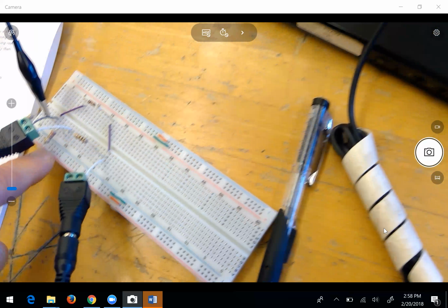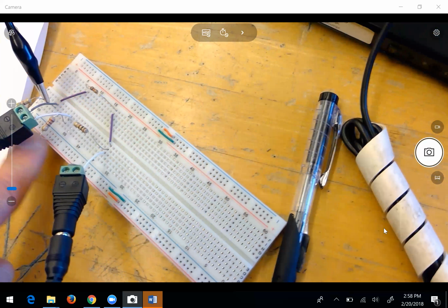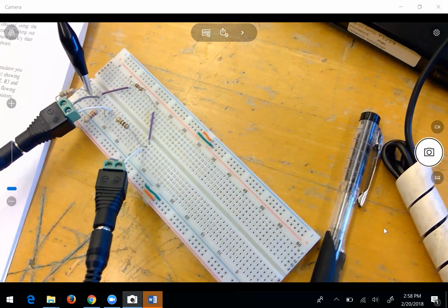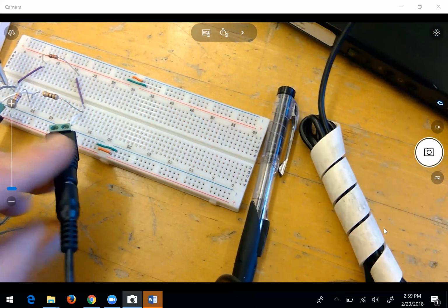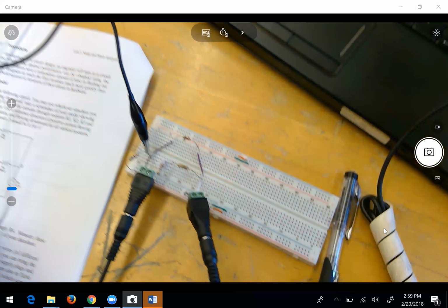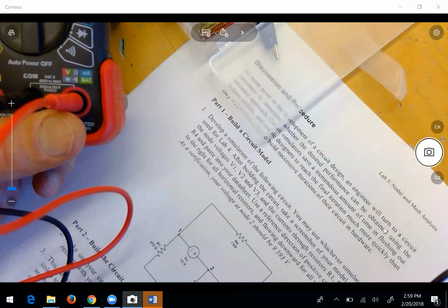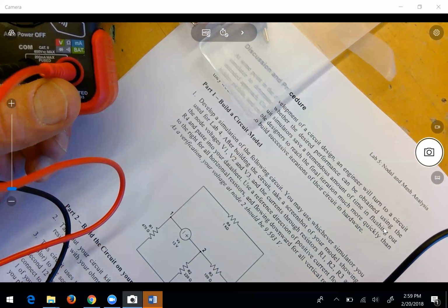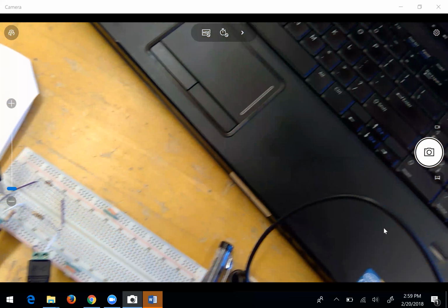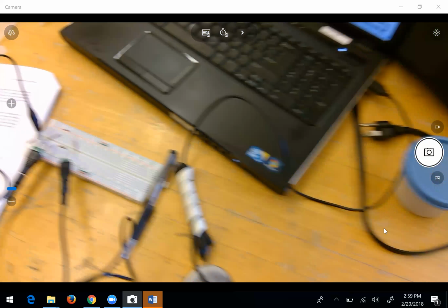Yeah. So this whole line here is all at your reference voltage, right? Oh. So the voltmeter has to have what's called the common side. Common is going to your reference, and then this is going to go to V1. And when you do that, you're going to measure V1 volts. Okay, and then you do that for 2 and 3 as well? Yeah, so basically once you attach this black wire to the reference node, you can just probe the other node voltages by moving the red wire to the different points of your circuit. Okay. That makes more sense. Good.